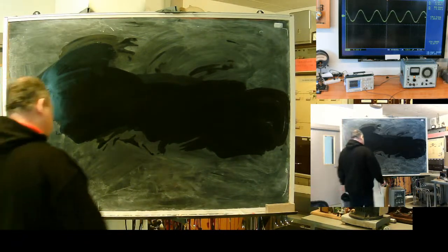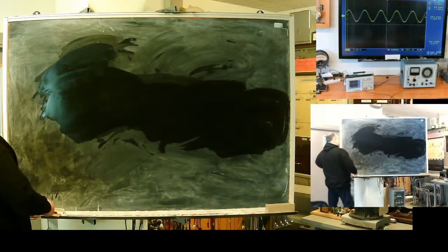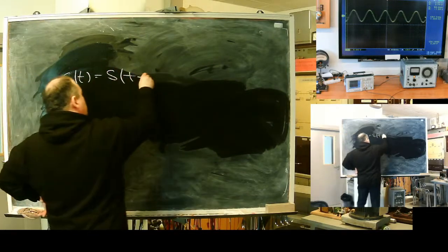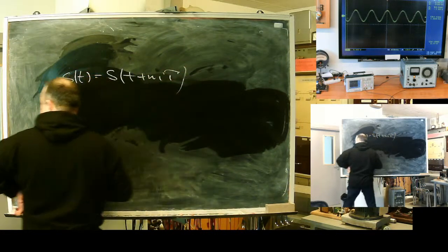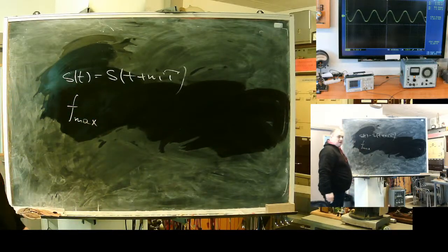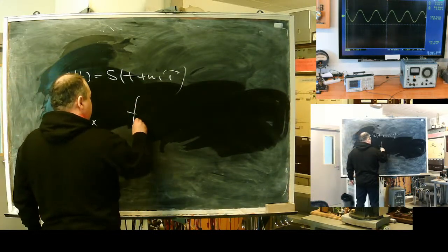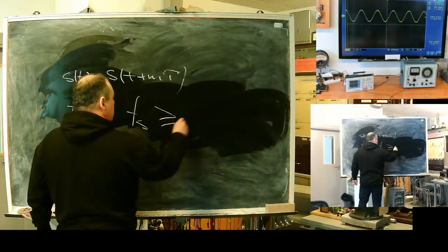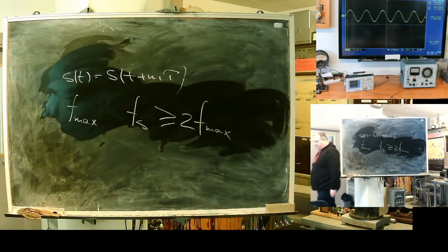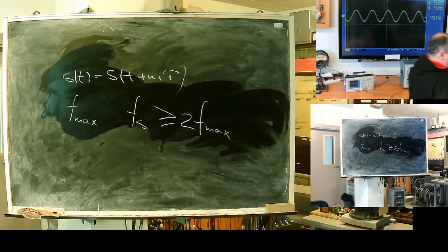Nyquist's idea, from 1938, is this: if we have a periodic signal, and the signal's highest frequency is F maximum, the sampling rate, or discretization frequency, F sampling, should be at least twice that maximum frequency. So we need at least 2 points, but not on the basis of the signal period.